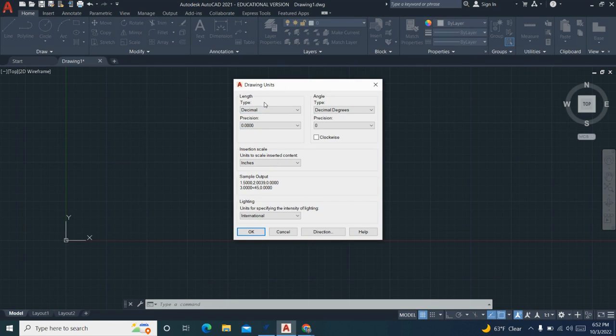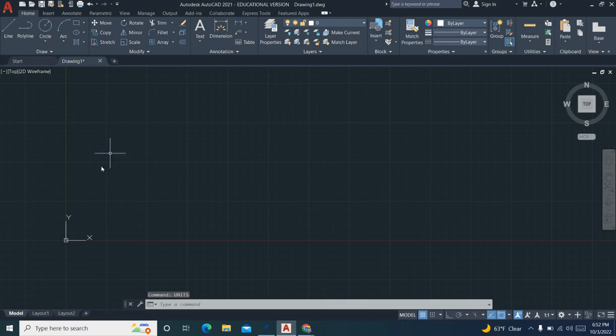Now, when I do all my work in V-Carve, I like to make sure I'm in architectural units, and I keep mine set to 1/16. So if you want to be super detailed, go to 1/32, 1/64, 1/128, whatever, so on and so forth. Good for you. Everything that I do in here is going to be to a 16th. So that's where I leave it. But having architectural inches, imperial units, is very important. And it just helps transfer your file properly.